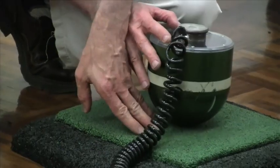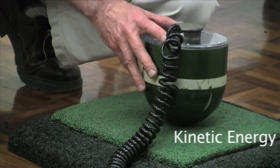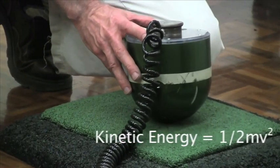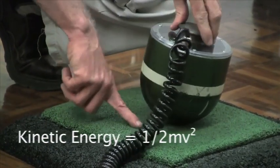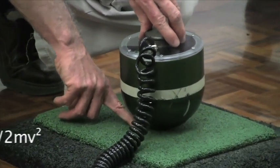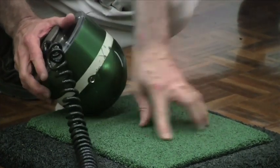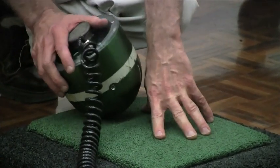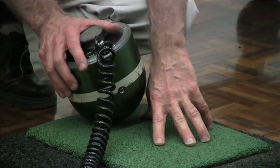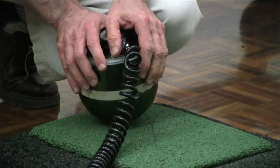So maximum kinetic energy is a half mv squared. We know how many joules we have, mgh, and that should equal a half mv squared just prior to impact. When we impact, we do work on the surface, and the work is the force times the distance, and the distance is the penetration into the sample.